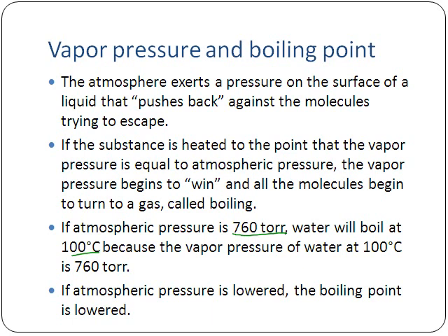Now, if you think about this, there are two ways then to boil water. One of which is to raise the temperature of the water so that the vapor pressure of the water increases. If the vapor pressure gets to the point where that vapor pressure is equal to atmospheric pressure, then we know that basically it'll boil. This is sort of like this. I have atmospheric pressure that's right here. I have my vapor pressure that's right here. As that temperature goes up, the vapor pressure rises until the point where they're right on equal. When they're equal, I've got boiling.